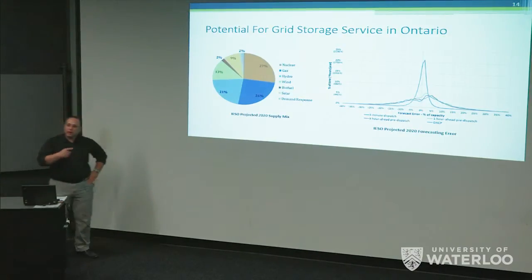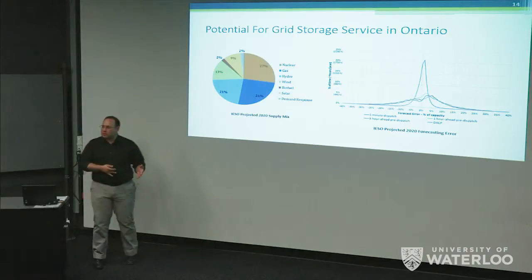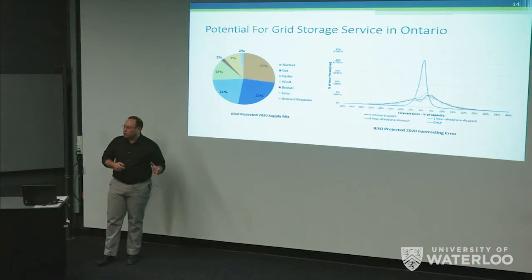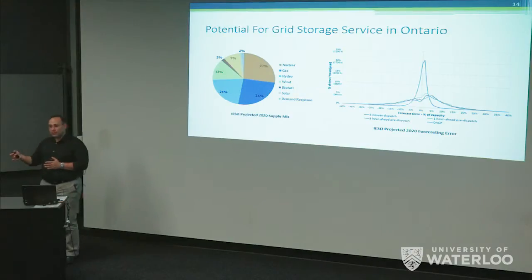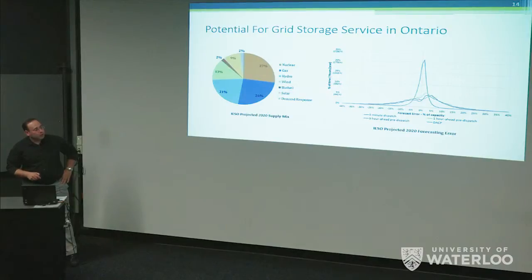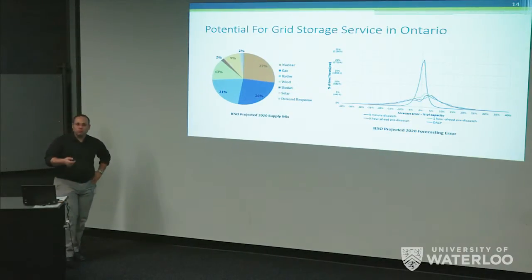And that is where CAES, with the right design, can operate quite well, because right now the response time is about 15 minutes, which is what it's designed for. But what CAES can do is operate with a 10 to 5 minute response time, which then lets it operate here. That means it can charge or discharge, or have a cycling of about 4 times a day.